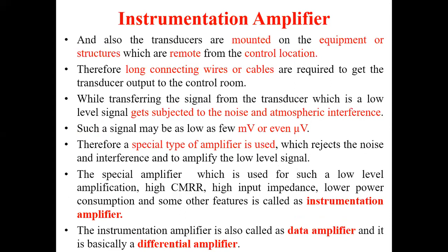Since these signals are very low level, when they travel through the cables they are subject to noise and atmospheric interference. Because of that, the quality of the signal reduces because of the addition of noise. This type of signal cannot simply be amplified, because when it is amplified directly, the noise amplification will overcome the actual signal.